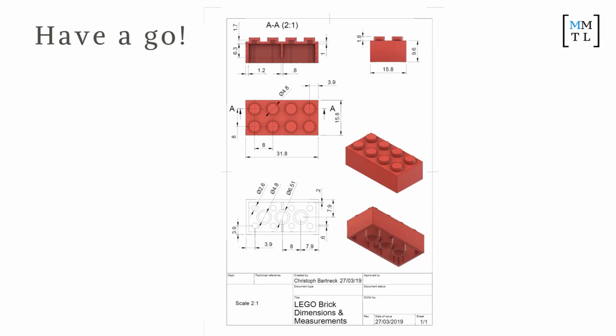In the sketch, the body. That looks better. So the cylinder distance is 1.8. That's how you make sure that the distance is right. You can delete the circle if it's not right, and then just start again from the bottom of the part, which is 1.2 down. To where we need to cut is 1.7. Because it's 1.2 down, 1.7 minus 1.2 is 0.5.